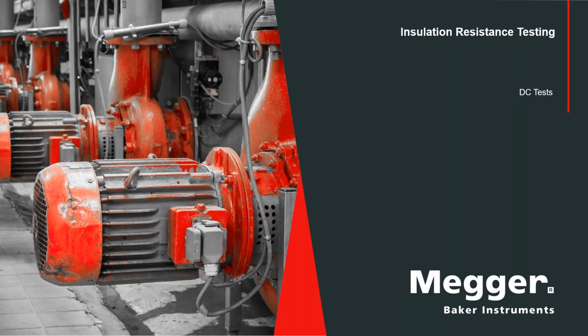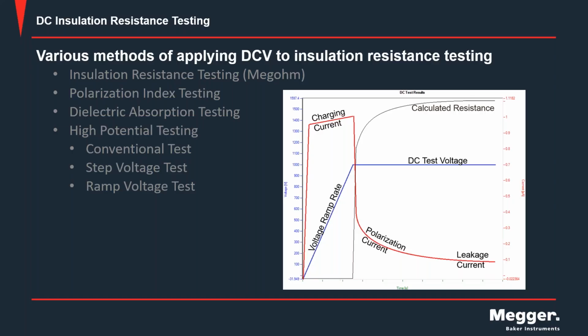The next tests we will proceed with are the DC tests, and the DC tests include the MEGGER test, the PI, the polarization index testing, DA, which is dielectric absorption testing, and high potential testing, which would be a conventional high pot, step test, or ramp test. Here we're going to apply various methods of applying voltage to the system and see the reaction through the leakage current that occurs there.